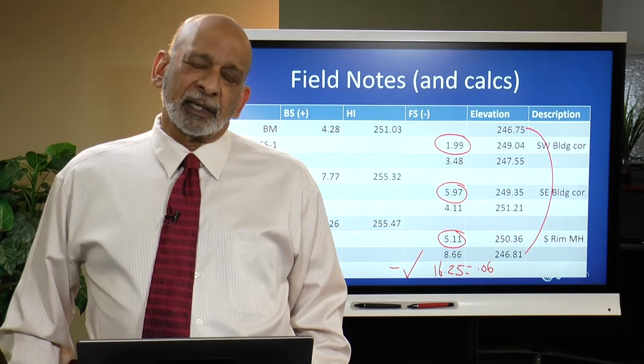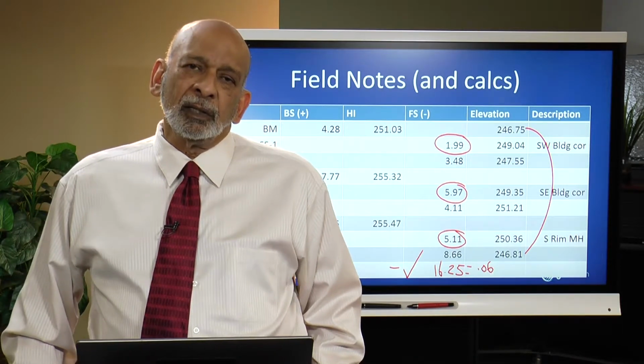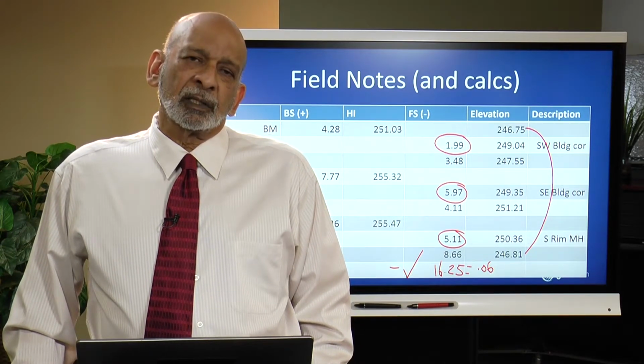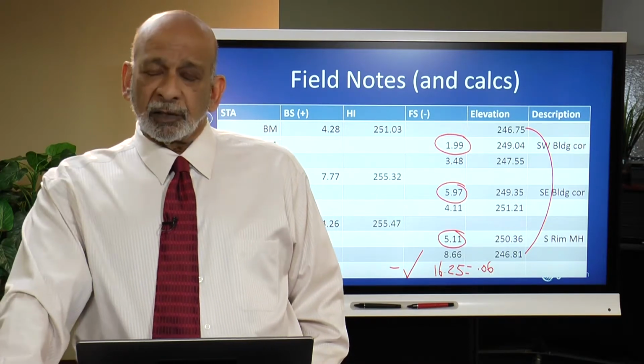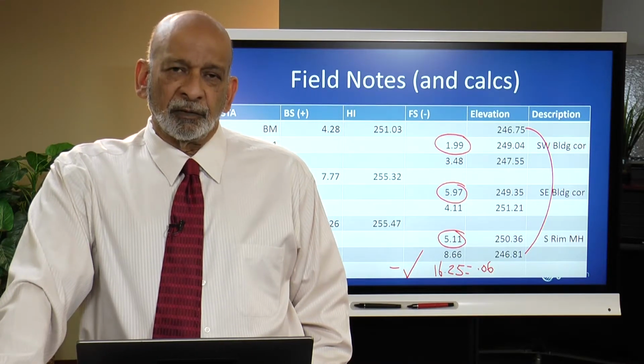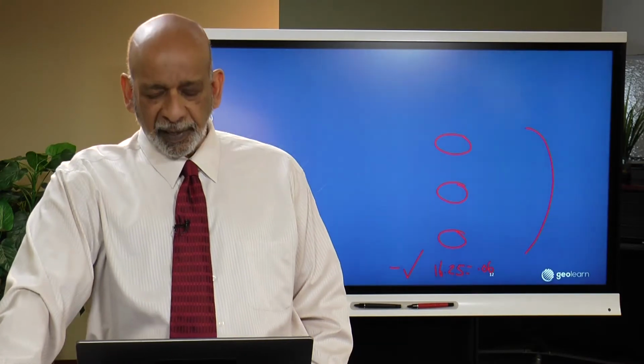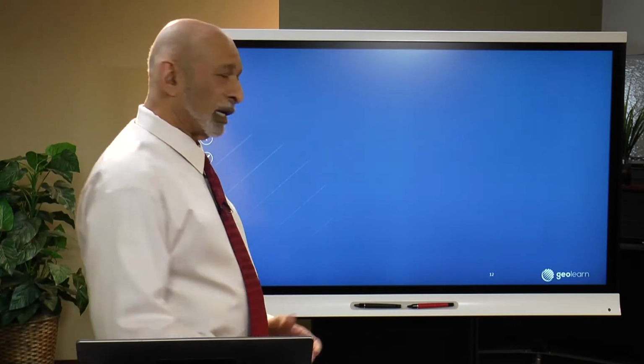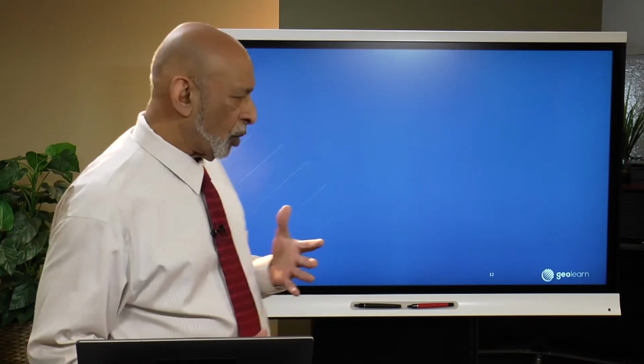you have done that. As I said, you need to carry them as you go along, and you do not ever submit, whether it's a homework assignment or lab project, or actually when you go out in industry and start working, do not ever submit field notes without performing the math check. And so that concludes this particular discussion of the leveling process. Hopefully you will get used to this, because these are really some of the first few sets of surveying measurements that you're doing. And there are lots of things that I want to point out that can happen in the field that can cause problems.